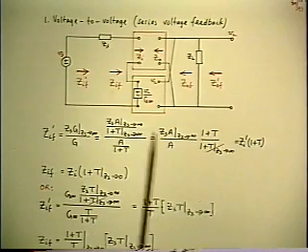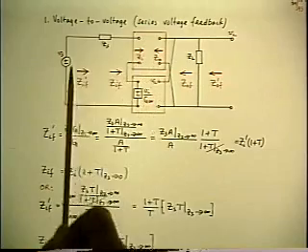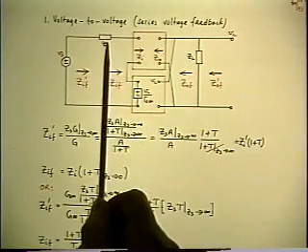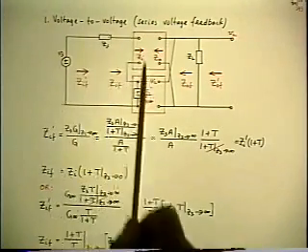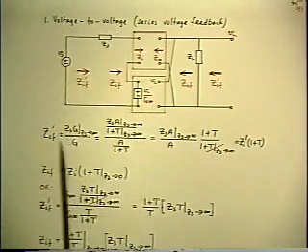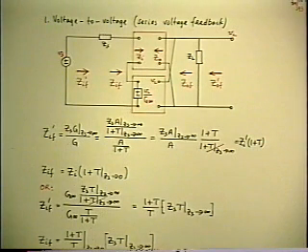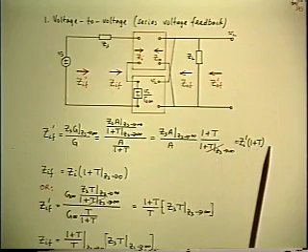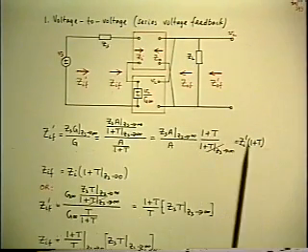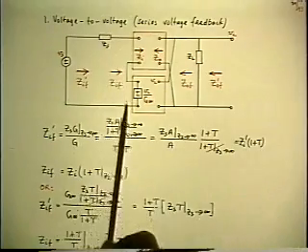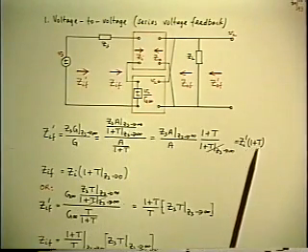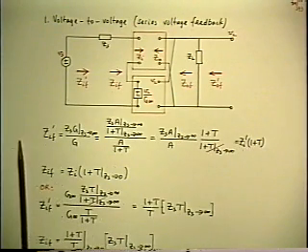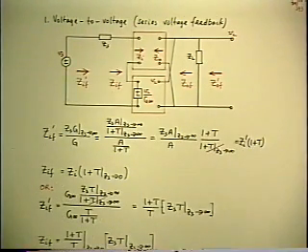One of them is T as Zs goes to infinity, which must be 0, because if you let Zs go to infinity, you're opening the voltage differencing loop and killing the loop again. So that must be 0, and all that's left is the 1 plus T. And you get the well-known result that series voltage feedback to the input raises the outside input impedance from its open loop value to its closed loop value by the feedback factor.